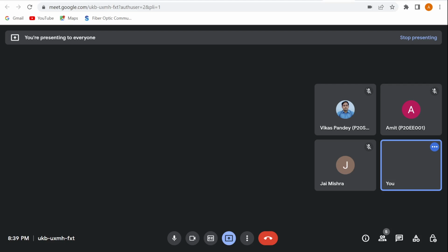So X(ω) equals the integral of x(t) e^(-jωt), and here you have to put delta(t) equal to 1. As the impulse function exists only at t equal to 0, the integral from minus infinity to infinity is equal to 1, so e to the power minus 0 times t equals 1. Okay, so this is in the frequency domain. So the impulse function is also an impulse train only. So these three options are correct.